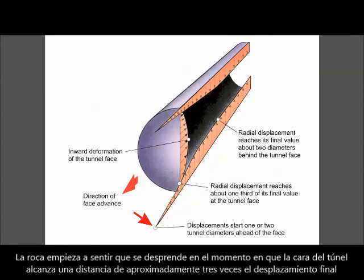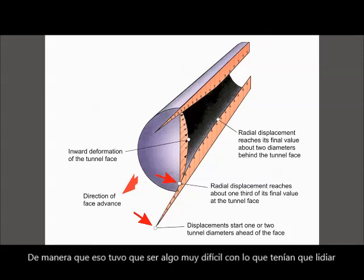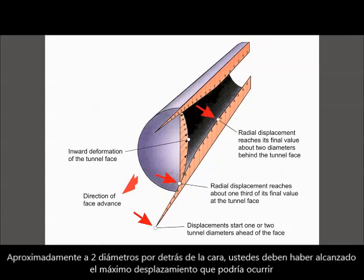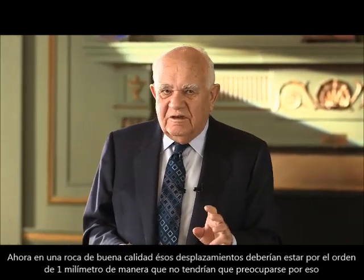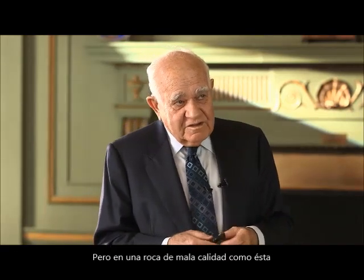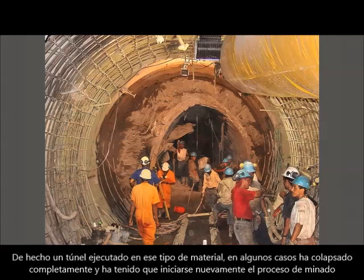By the time the tunnel face arrives, about 1/3 of the final displacement has already taken place, and that's shown by this point here. And obviously the tunnel face is also bulging inwards, so that has to be thought about and dealt with. And about 2 tunnel diameters behind the face, you've reached the maximum displacement that occurs. Now, in good rock, these displacements might only be a millimeter or so, so you don't worry about them. In bad rock, such as this one, the maximum displacement here could be 1 or 2 meters. In fact, the tunnel, in some cases, closed up altogether, disappeared and had to be remined.